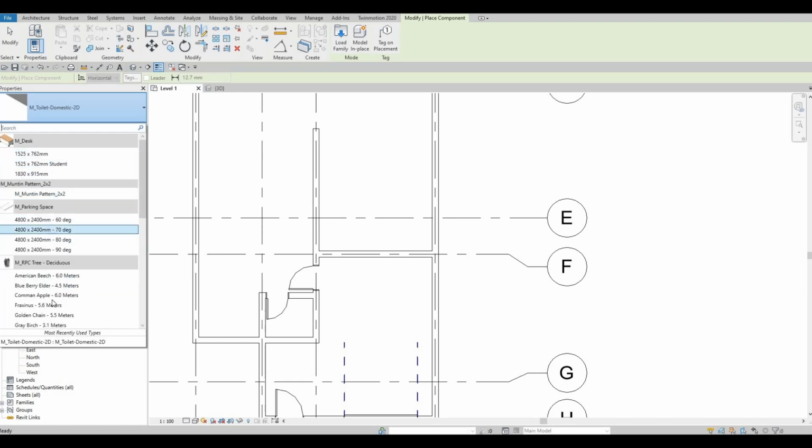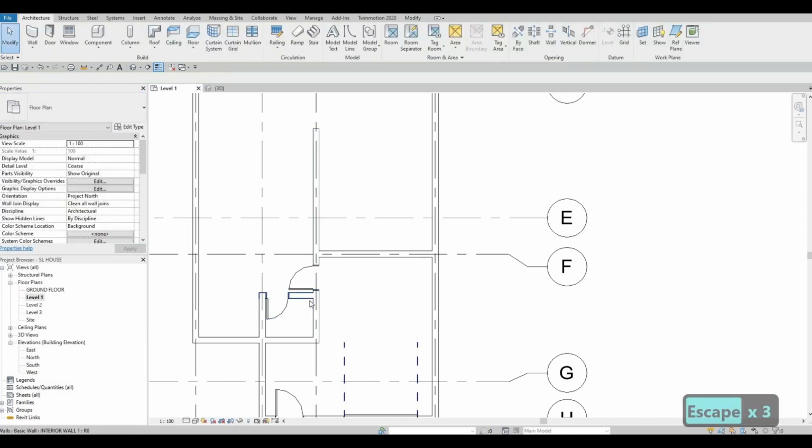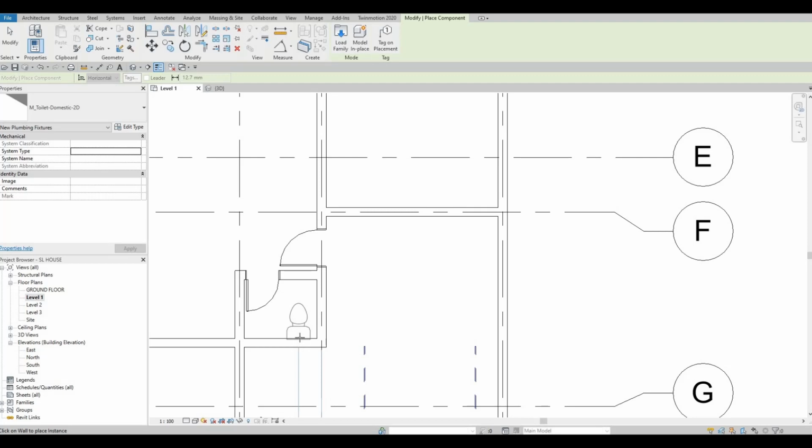And sometimes you loaded so much right here that it's not easy anymore to look for it. So right now, instead of clicking right here, you just type in CM. That's the keyboard shortcut, and then let's add it right about here.